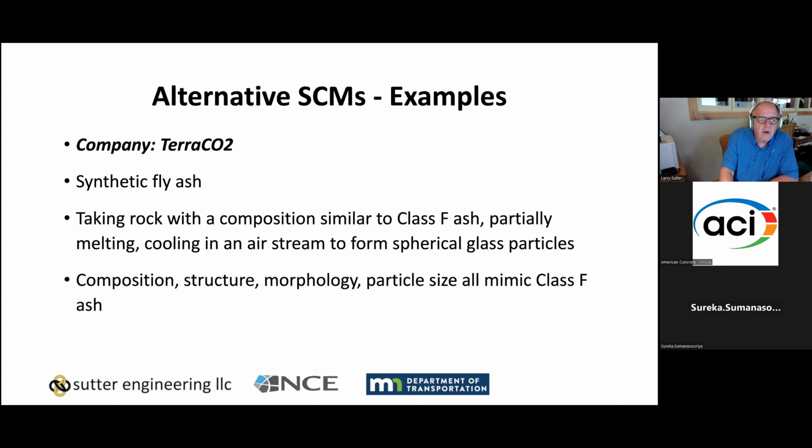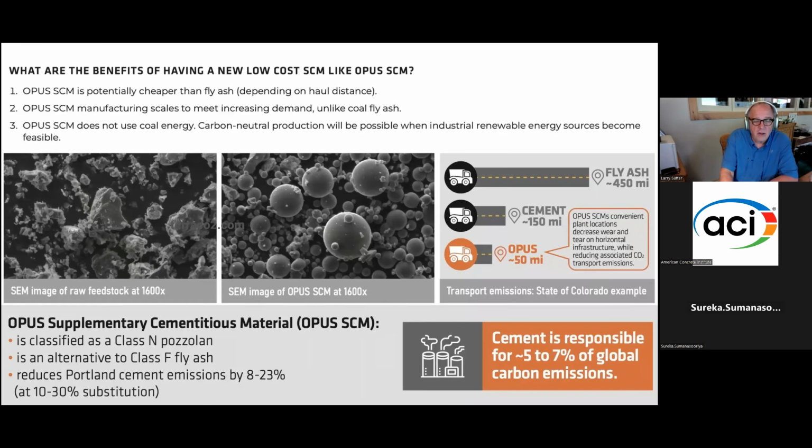Terra CO2 is a very interesting company. They're producing what I call a synthetic fly ash. They're basically taking silicate rock with a composition similar to a Class F ash, and then they go through a process of partially melting and cooling this in an airstream to form spherical glass particles that resemble fly ash. The composition, the structure, the morphology all look like a Class F ash.